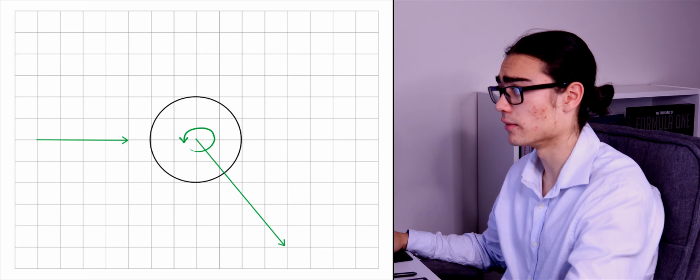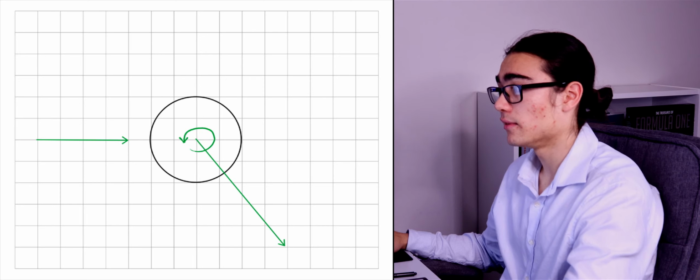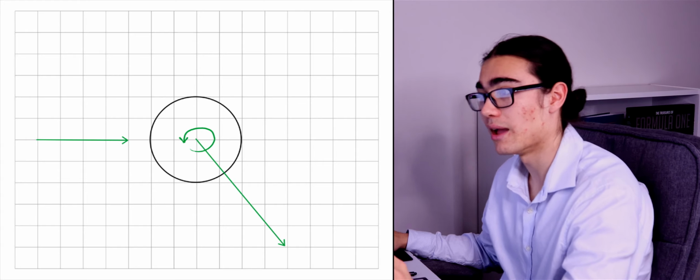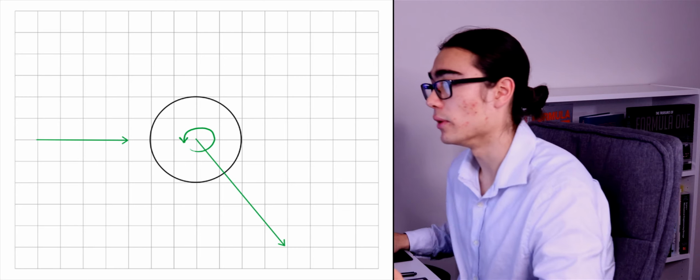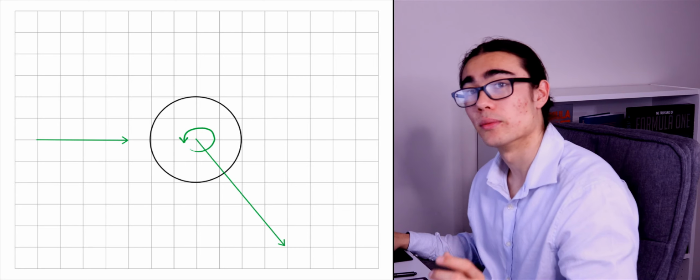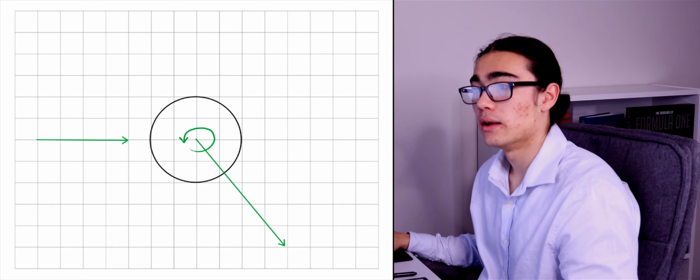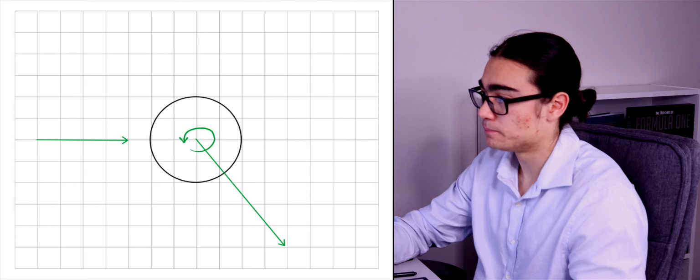This is what we normally expect. But let's assume that for this case, we're very close to tripping to turbulence. So we're in laminar flow, but we are very close to tripping into a turbulent boundary layer. Let's go ahead and draw out our boundary layers.